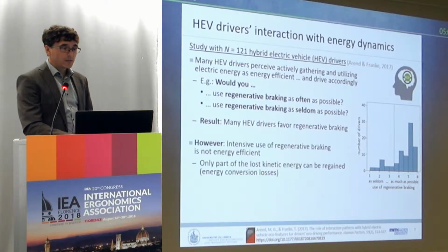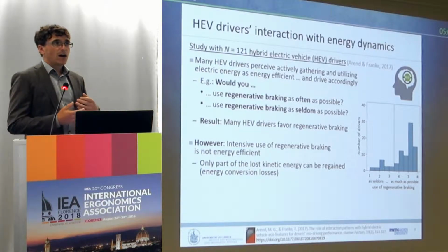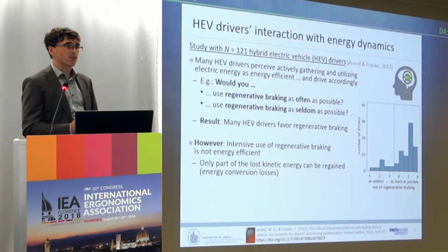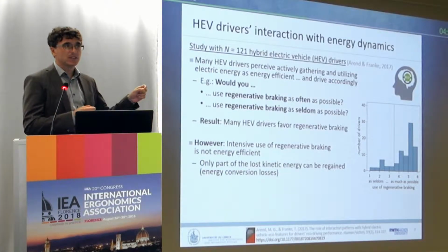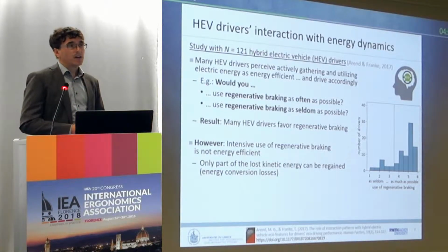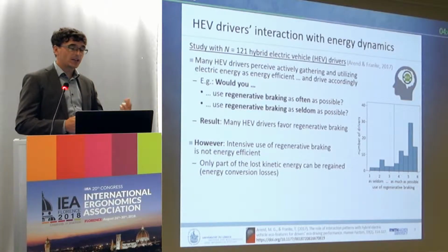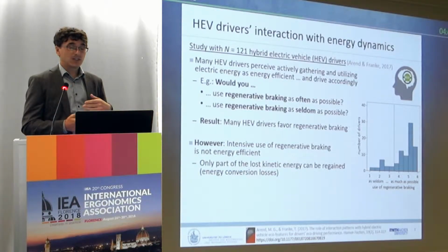So it seems, and if we think about it, it also becomes clear that intensive regenerative braking is not a good idea. It's not energy efficient, for example, because only part of the kinetic energy that you regain can actually be used later on, because there are lots of energy conversion losses. And that's not the only thing.